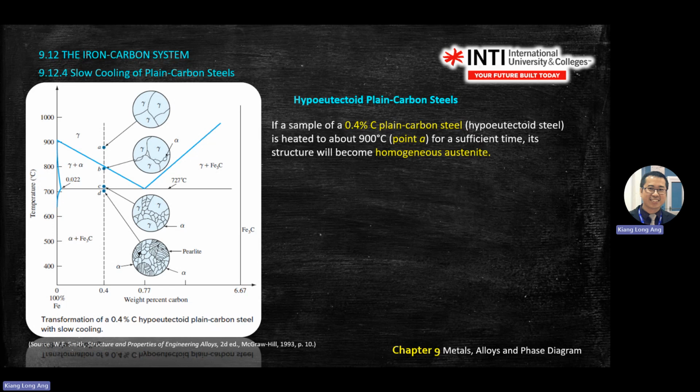Okay, so again, in material, don't go and draw the alpha inside here. It grows on the space here. Means between the two grains, there's a gap there for it to grow. It will grow on the gap. So don't go and draw it inside there, because inside you already have all the metal. How can it suddenly go inside? It cannot. So it will grow at the boundaries there. You see, draw it on the line here. So the line will grow a little bit.